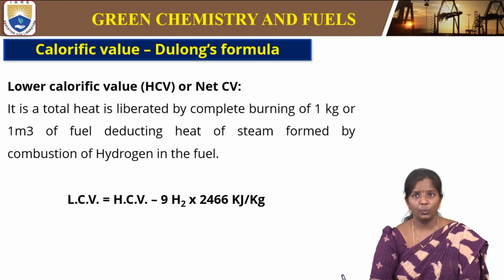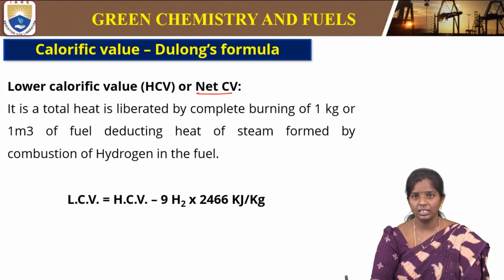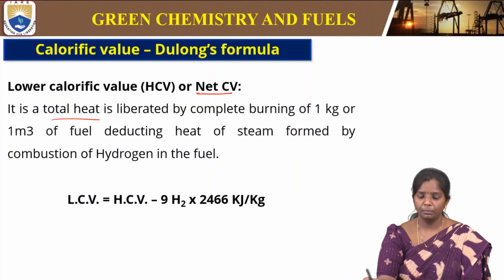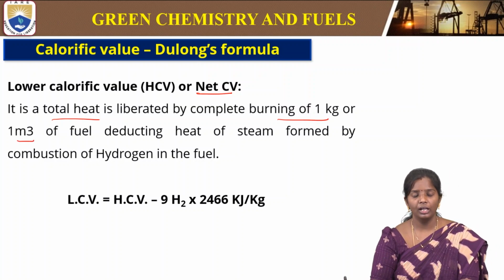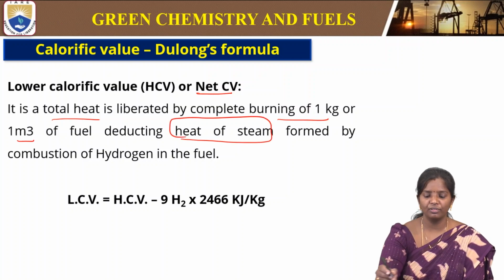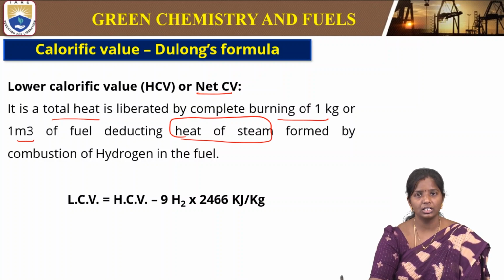The next is the lower calorific value or the net calorific value. What is this lower or net? It is the total heat liberated by complete burning of 1 kg or 1 cubic meter of fuel, deducting the heat of steam. The heat of steam is not useful for running automobiles or machinery. Therefore, we are not considering this heat of steam in the net calorific value.